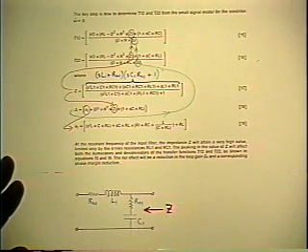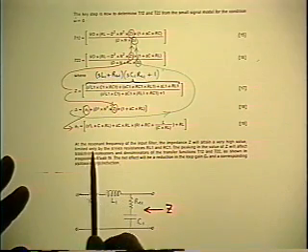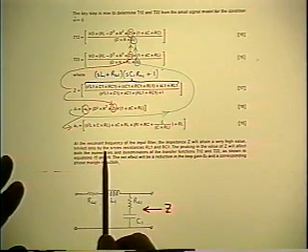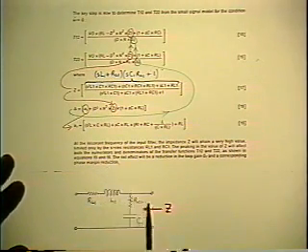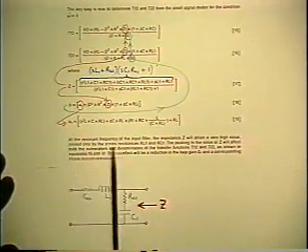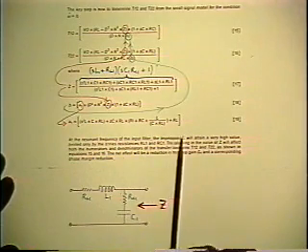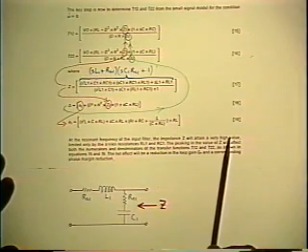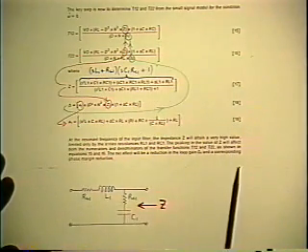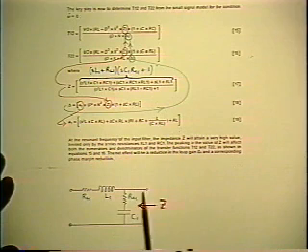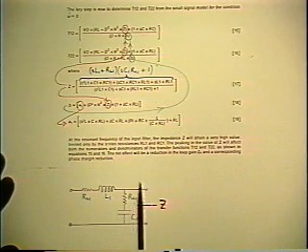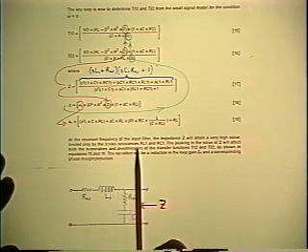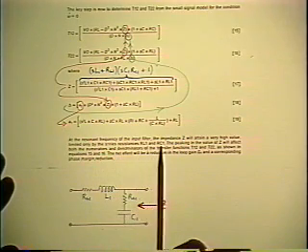That's correct. But what is it he wants to do with this? Look what he says under here. Well, it doesn't matter. I'll just say what it is. At the resonant frequency of this filter, the impedance Z, its output impedance, will attain a very high value. And that's what he's concerned about in the whole paper, the maximum value of this output impedance, limited only by the series resistances RL1 and RC1.